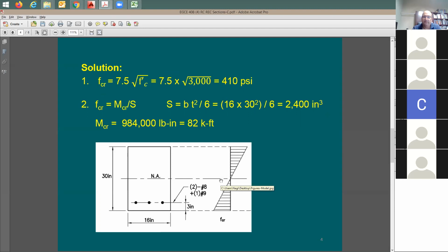So in this exercise, what I have done, if you recall, I ignored the top reinforcement. I didn't give you any beam with some top reinforcing here, right? It is usually just the tension reinforcing, which we call the compression or the hangers reinforcement. And I consider the beam design here to be a rectangular section. In reality, most likely, in 95% of the cases, you're going to have a T section that I'm just ignoring the T for now.